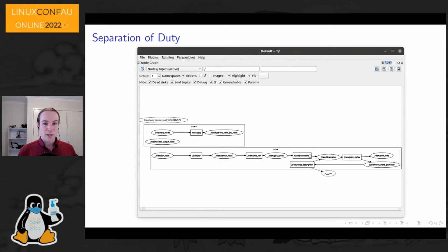The rest is all on my laptop. All of the inverse kinematics, all of the joystick handling, all of the everything else. The ROS2 nodes automatically discover each other over the local network. ROS2 transport layers are deeply configurable and do support encryption and authentication. The hard work is all done on the laptop, while the robot can focus on doing things and measuring things.